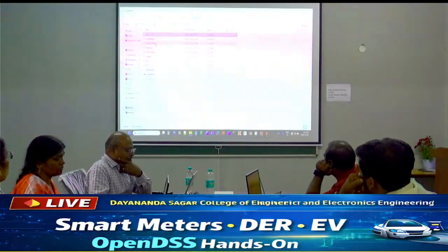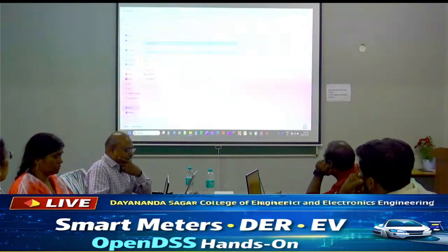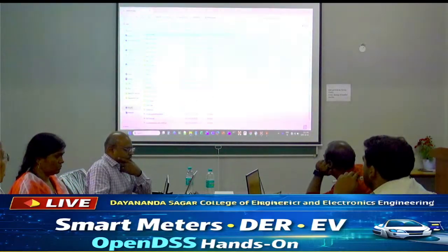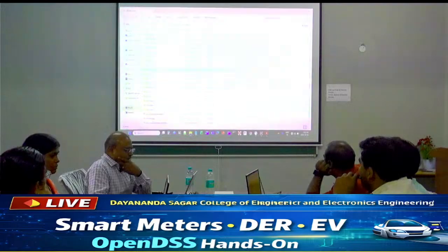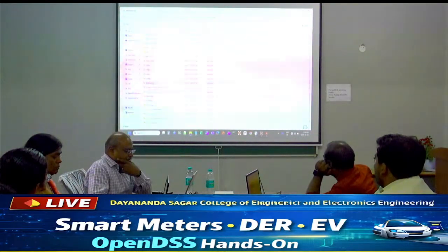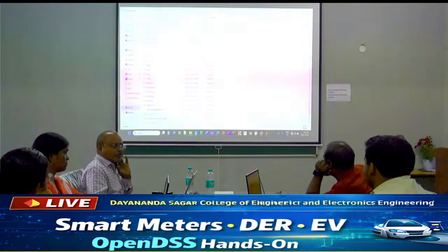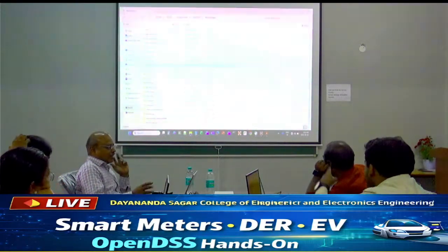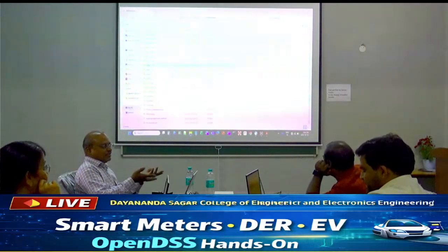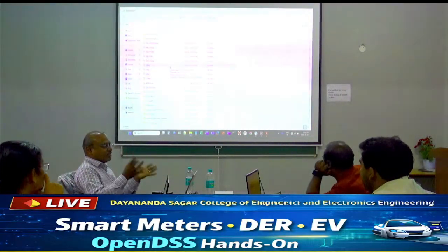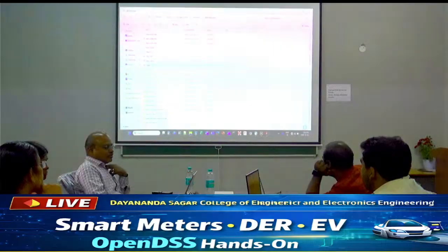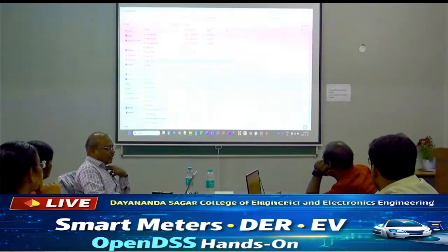And then you have the EPRI test circuits, and then you have IEEE test circuits. All libraries are there. So 13 bus, 34 bus, 37 bus, 123, 8500. So all these IEEE bus circuits are already given to you in OpenDSS format. So you can directly take this and open it, make whatever changes, and run your simulations. This is a very good set, you can just go and explore.